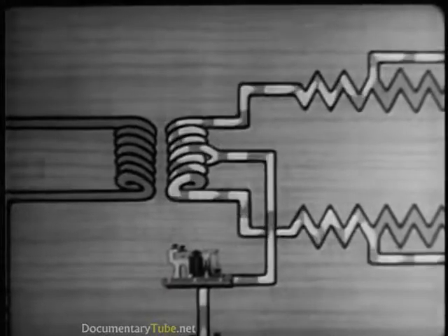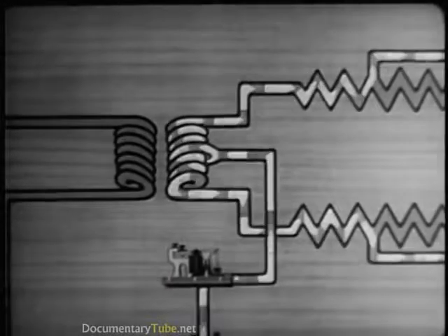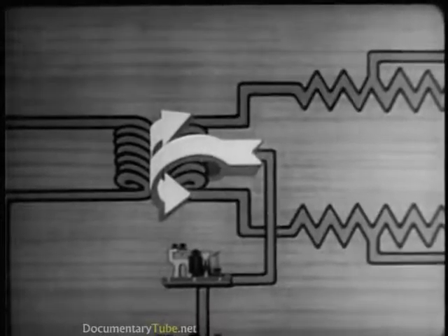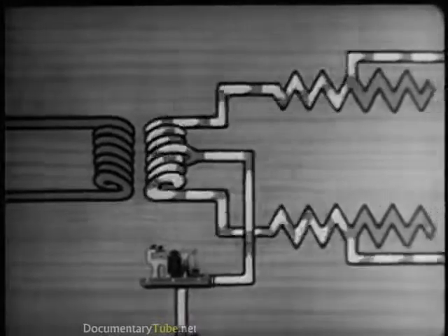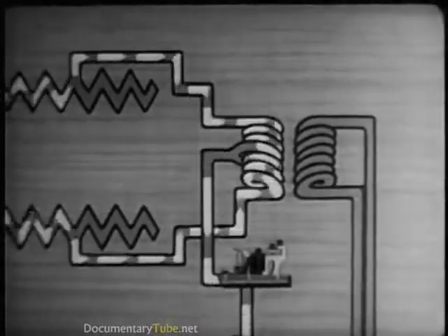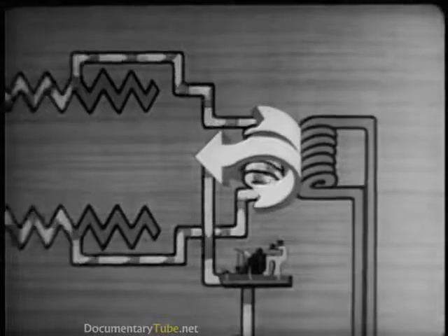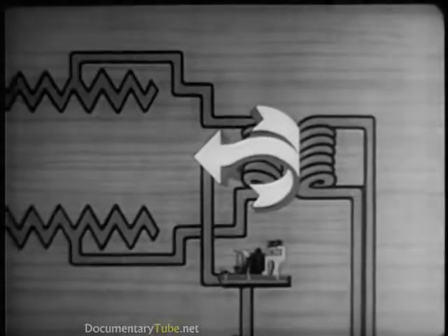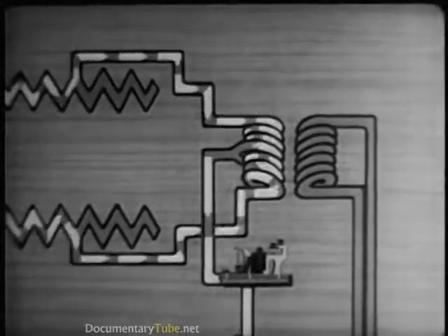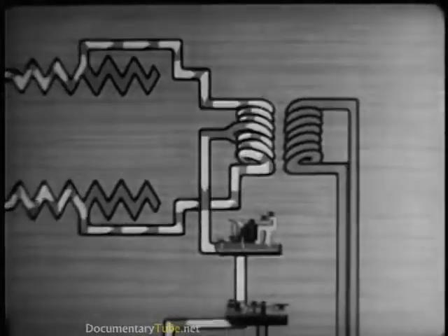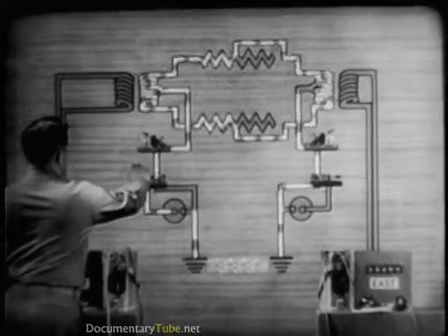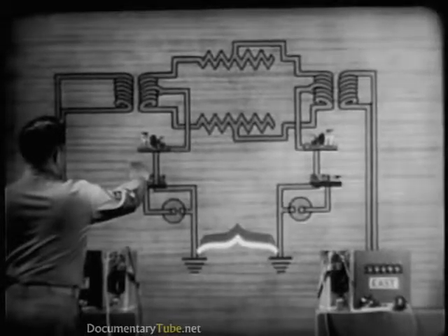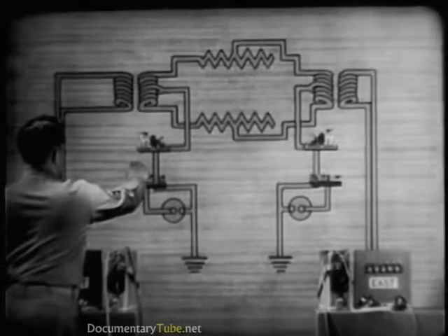Since both line wires are of equal resistance, the current divides equally in the repeating coil. The currents continue through the line wires until they meet at the midpoint terminal of the other repeating coil. Here, the current becomes 1 again and flows into the east telegraph set. The circuit is completed through the earth. The telegraph current doesn't interfere with the telephone circuit, and here is why.